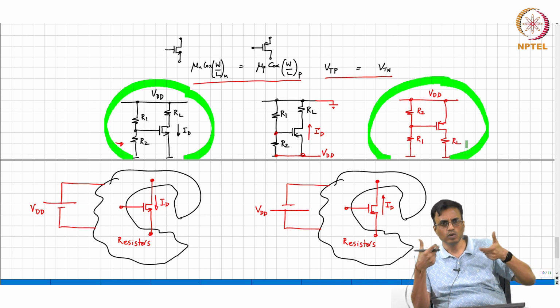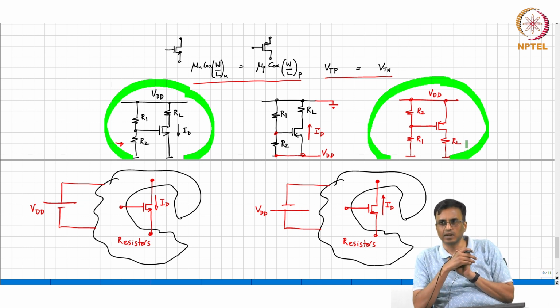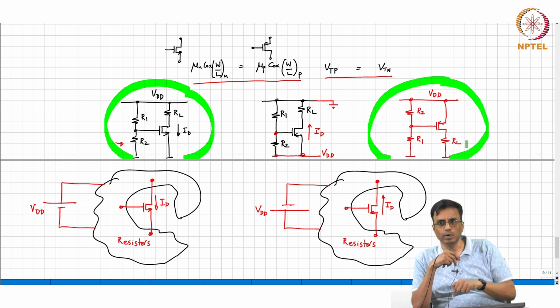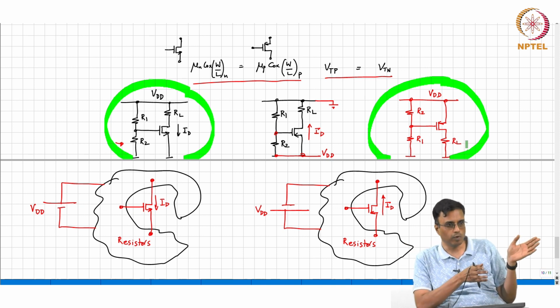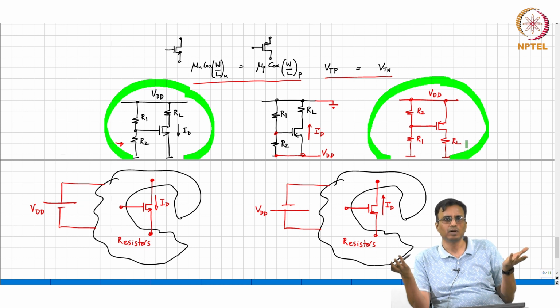And then since the directions of the currents are all going upside down, you turn the circuit upside down, and therefore you will get a PMOS circuit which operates between positive supply and ground, and where current flows, of course, always from a positive potential to a lower potential, but on the page it will flow from upwards to downwards, right. So by attending this class, you basically doubled the number of circuits you know, because every circuit you knew before can be converted into something with PMOS.